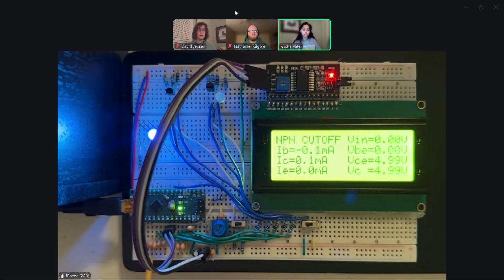At each of these analog nodes, we also have a decoupling capacitor that bridges from the analog node to ground, and again, it's there to smooth the signal and eliminate any unwanted noise.